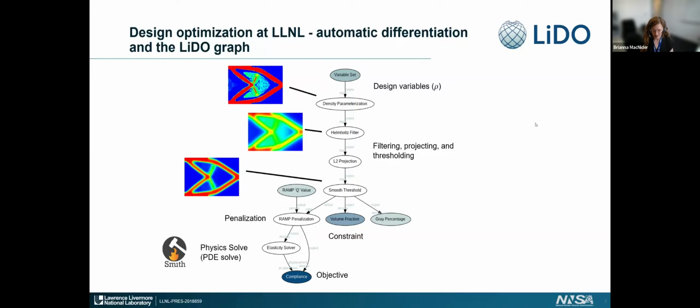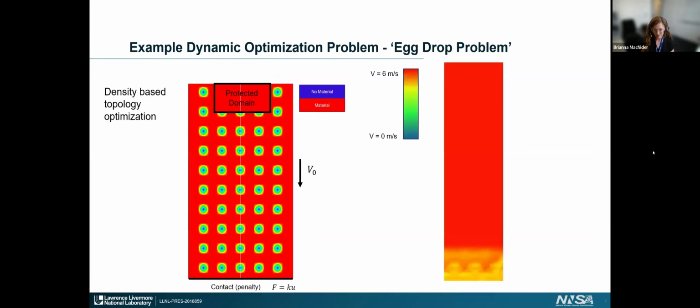Secondly is that this is parallel enabled. So the nice thing about this is we can throw it on the supercomputer and run problems with lots of degrees of freedom and lots of time steps fairly quickly. And I have just represented here some snapshots from a problem that was run with a very classical cantilever beam density-based topology optimization problem. We're not limited to that. We can do different sorts of optimizations with this setup here.